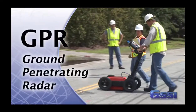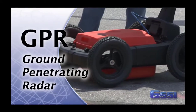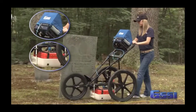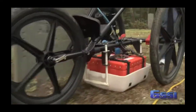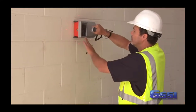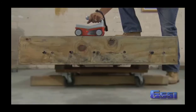GPR stands for Ground Penetrating Radar. It's an electromagnetic energy signal that penetrates through the subsurface. GPR systems are typically comprised of three elements: the control unit, the antenna, and the survey encoder. Depending upon your application, your GPR system may differ from the one illustrated here. For example, the Structure Scan Mini contains all three components in one dedicated system.